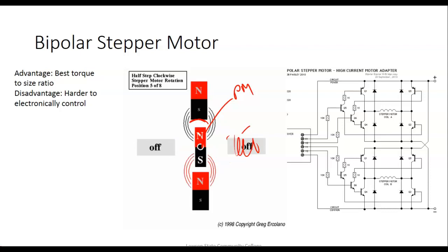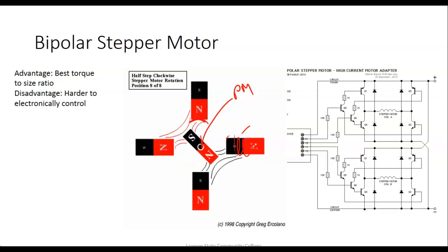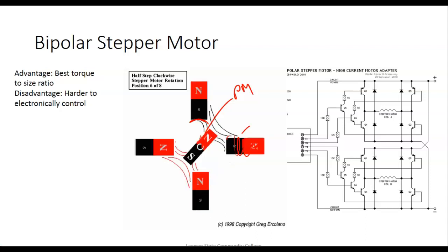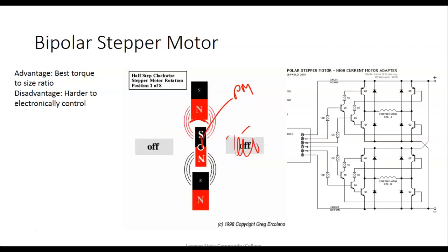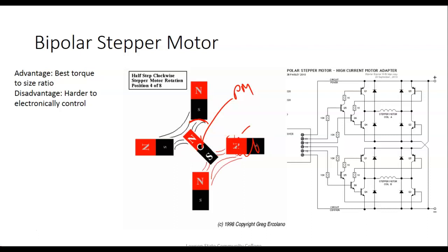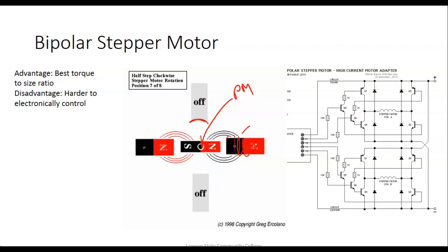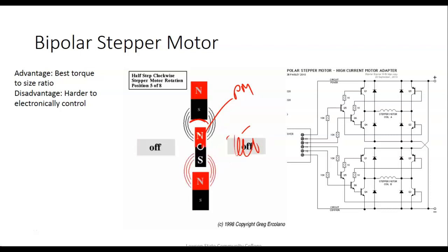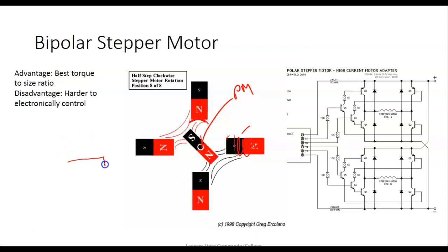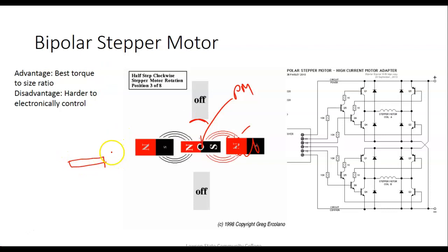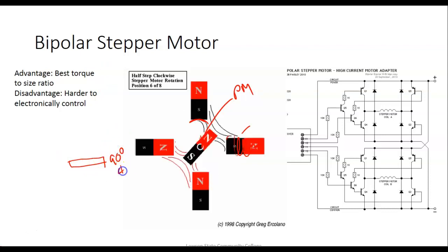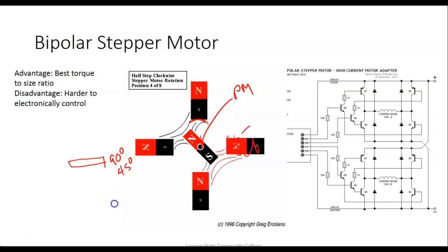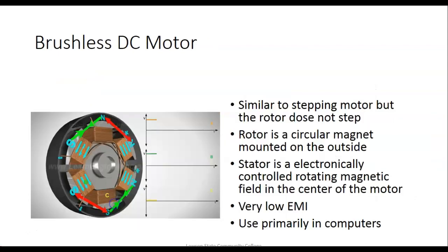And of course, this would be a controller for a stepping motor. And we have unipolar, we have bipolar, we have different types. The only stepping motor that we have is the one that's running the carousel on the Amatrol line. All the motors on the Festo line are, and like I said, it's really neat. It's only got 3 motions, and it's got the controller built into the thing. And it's been programmed to either move 90 degrees or move 45 degrees from its current position. So it takes very few wires to run it, and you just say move 90 from your position or 45.